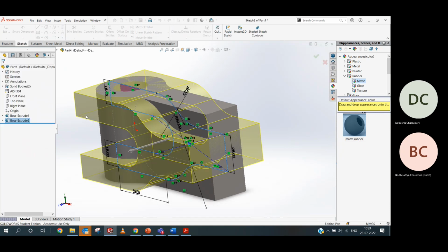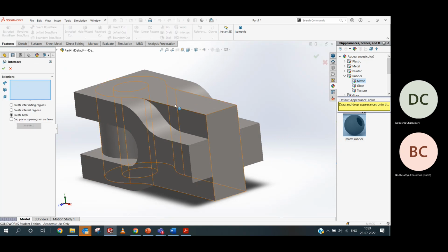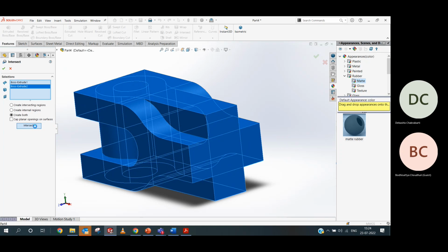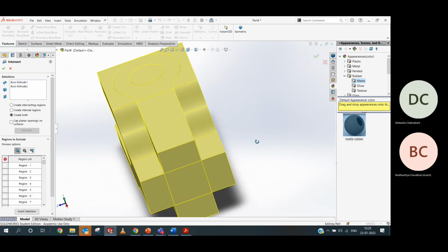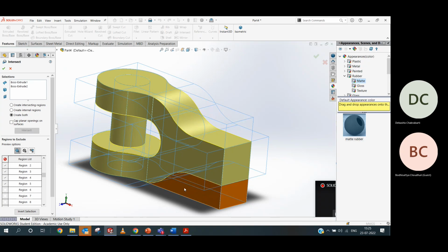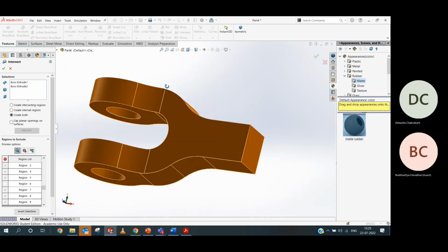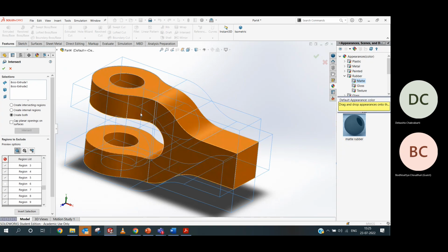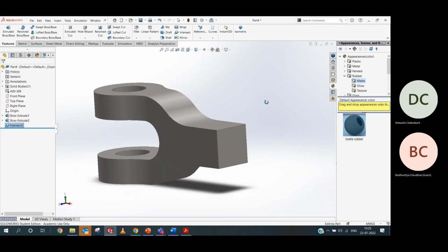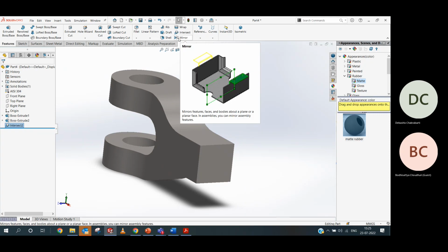So these are my two bodies here. Okay, this is a single body, this is a single body. So the two bodies are different, which is not merged and which is interconnected with each other. Okay, I just go for intersect here and select two bodies over here. Okay, go for intersect, and you select which one you do not need over here. Like I just don't want this and this. You just select over here, which you did not want over your model, and click on OK. So this is my whole model. Like that, I just use the intersect options over our drawing. Okay.